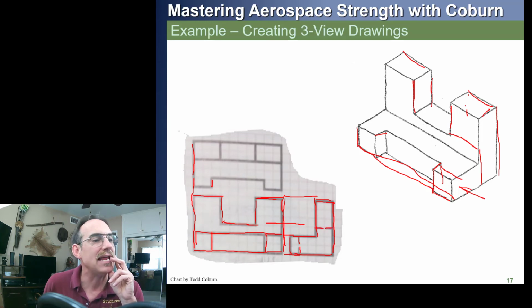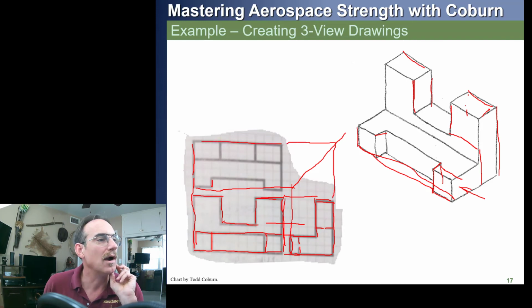Now, if we extend up the front face of this drawing and the near face of this drawing, then we put our miter line here, and then we can just bring these dimensions, and that will tell us where these lines go. This comes up to here and here, and so that tells us where these lines go.